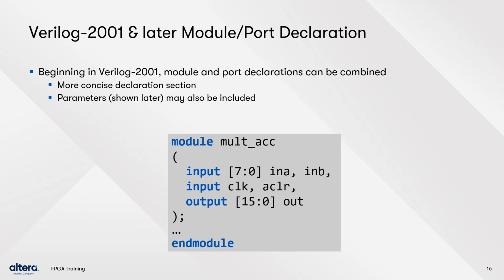With the Verilog 2001 standard, you have the option of declaring the port list and port type together with the module declaration. Here we see the same declaration as the previous slide, but in a more concise Verilog 2001 format.